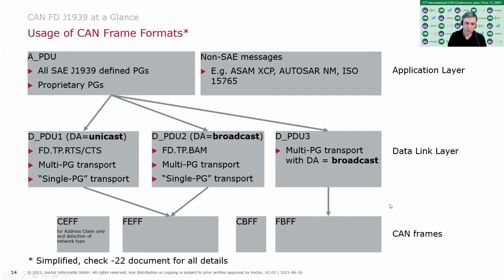You can use all 3 PDU types, but especially for the broadcast communication, which is the overwhelming communication scheme we have in SAE J1939. Therefore, you can decide on your own requirements if you would like to stay for those broadcast communications with 11- or 29-bit CAN identifiers. If you are going to use transport protocols, then you cannot use this by means of 11-bit CAN identifiers.